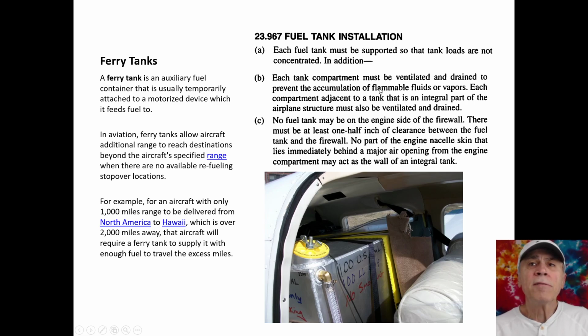Why am I talking about this? Fuel tank should be supported. Each fuel tank compartment must be ventilated and drained. No fuel tank may be on the engine side of the firewall. There must be at least a half-inch of clearance between the fuel tank and the firewall. No part, this one is clearly in the back seat, so it's not up by the firewall. And no part of the engine nacelle skin that lies immediately behind a major air opening from the engine compartment may act as the wall of an integral tank.